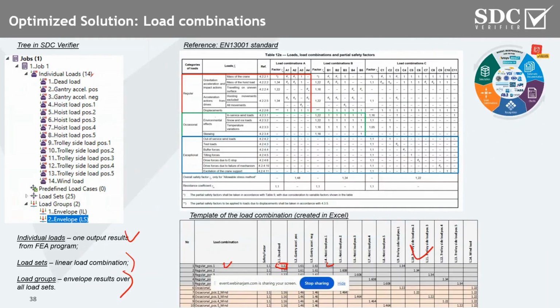So in short, if you got 100 or 200 different load cases, including wind influence, and you want to get a quick understanding of what's going on with your model, you get one picture for every single finite element. You get absolute maximum results from all load cases. Keep in mind that it does not happen simultaneously as one load case. It's impossible, but you have a kind of envelope of results that helps you to get an idea if you have any problems or not.